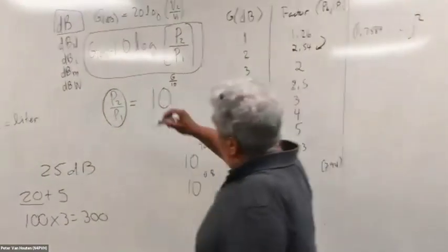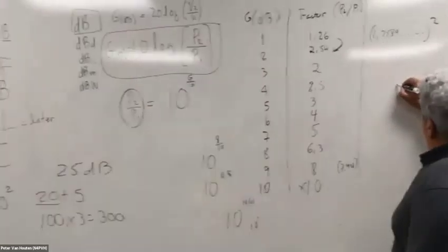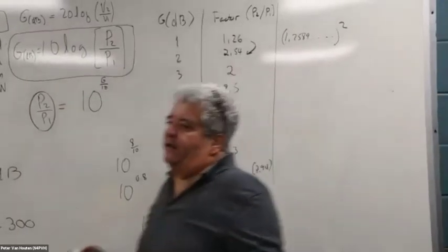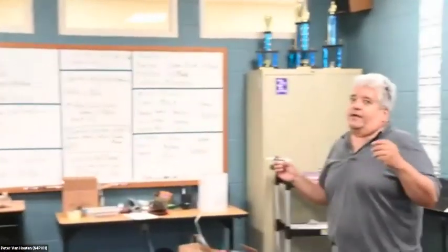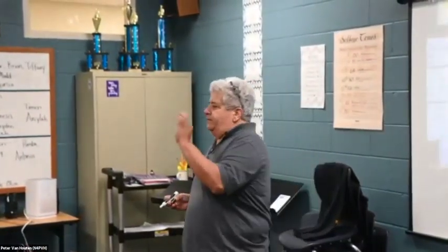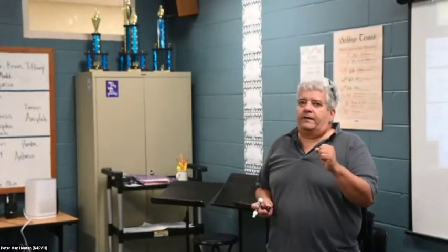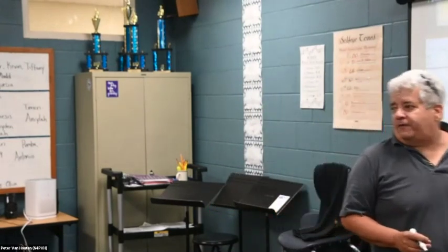So now let's go to dBi and dBd. There's a theoretical antenna that is called the isotropic radiator. It has no dimension. We cannot even in theory imagine it like a very short dipole; that would be an approximation. It's basically a point in space that radiates. It's an antenna that is not real. There's a mathematical definition for it, but it's used as a reference.